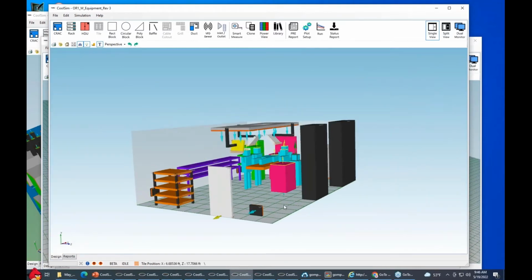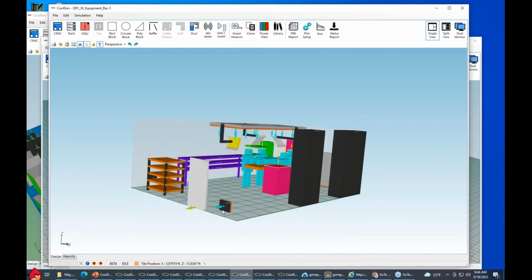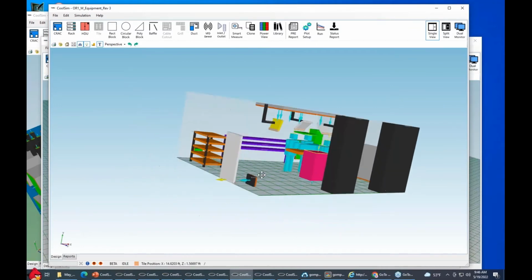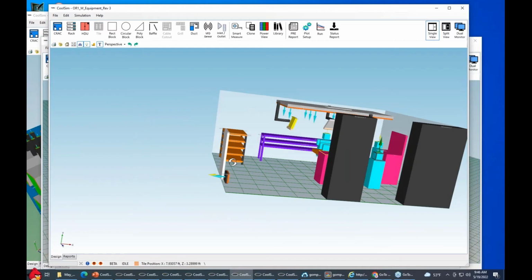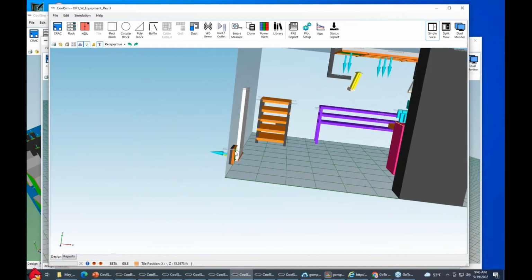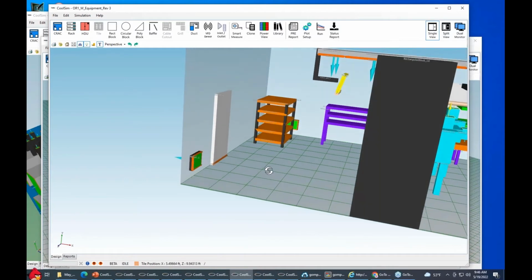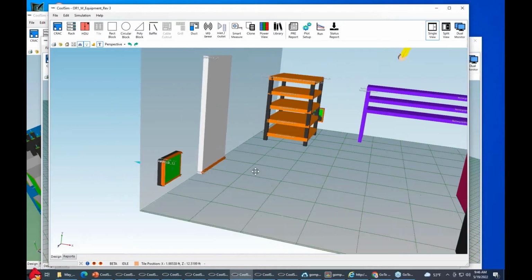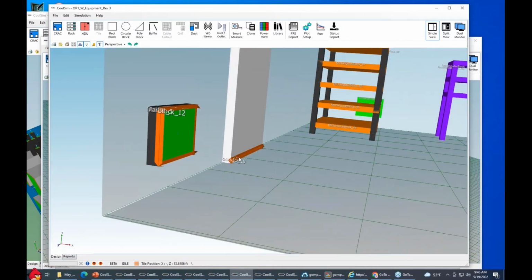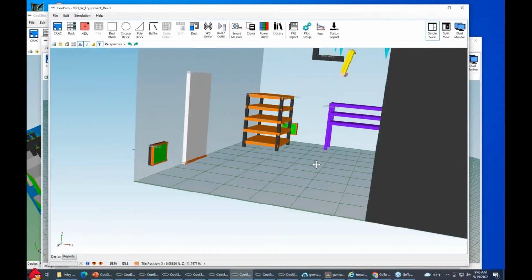They, in this case, want it, and of course we've got air going out of the walls down low. This is the proper design for operating rooms where you diffuse out through the wall. You're up off the floor. We also put doors in place and let it leak underneath the door as well. That's an outlet, general outlet. So I'm showing you this.